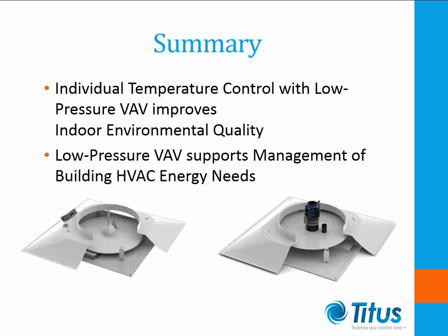Variable air volume diffusers provide additional solutions for the heating, ventilation, and air conditioning designer. With the flexibility of modulating air, they can improve occupant comfort while keeping equipment and installation costs reasonable. With square and linear diffusers, more architectural options are available. Finally, with electronic control, full integration with the building management system allows integration with an efficient and sophisticated system that maximizes indoor air quality while reducing operating costs.